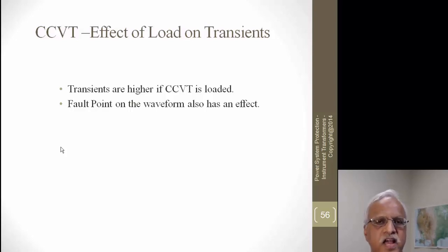As a recap of what we did on the instrument transformers: we know the two inputs given to the relay are voltage and current, and then we looked at the current transformers and reviewed the classifications of the current transformers, whether it is a metering type or protection type, based on the application.